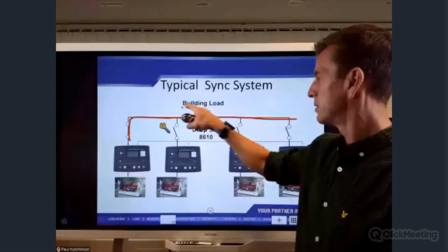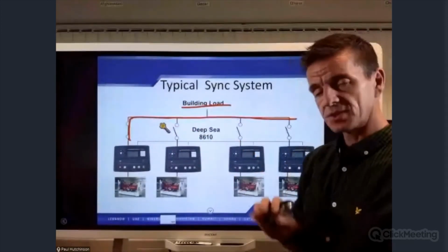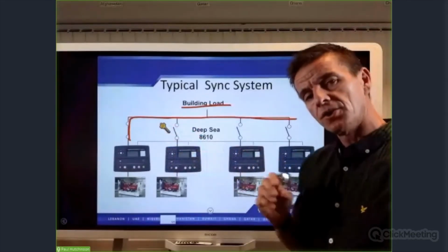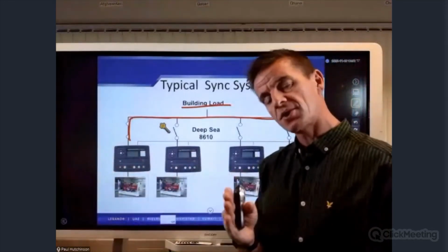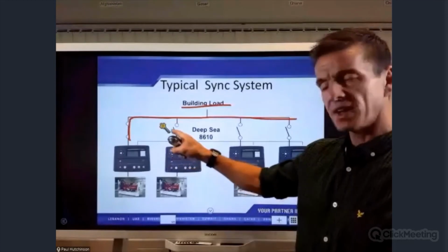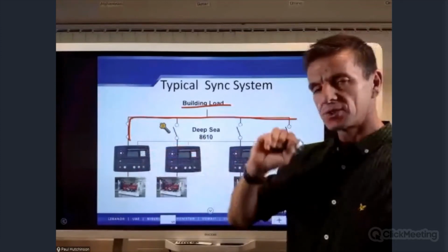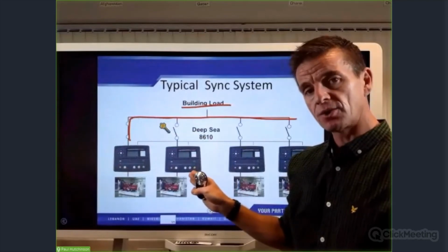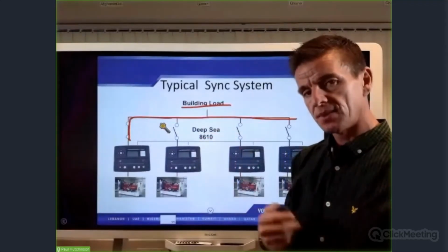As I say, we will have other breakers fitted downstream, obviously to stop one trying to feed onto the load. As I told you earlier, we have omitted it out. So all the other sets now have a voltage, frequency, phase angle, all of those things to start synchronizing and adjusting to. Each one in turn will take the key. Once number 1 has closed its breaker, he passes the token to the next genset, not necessarily the next one that's in line or in order. Remember, it's up to rated speed and voltage, and then it will try and synchronize.